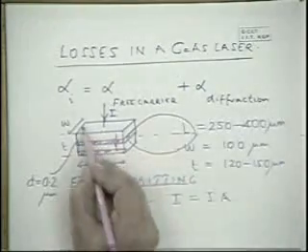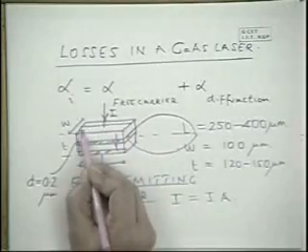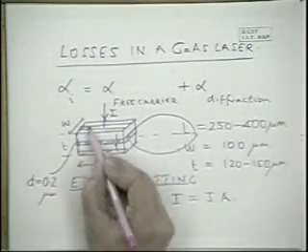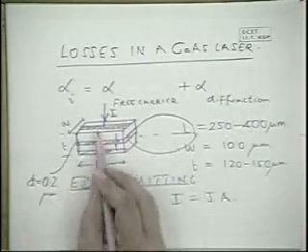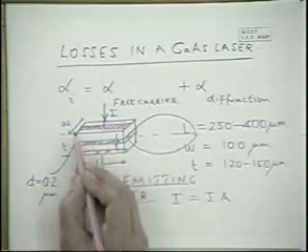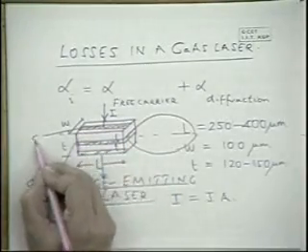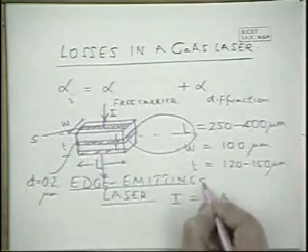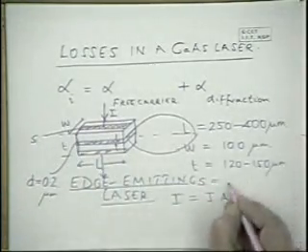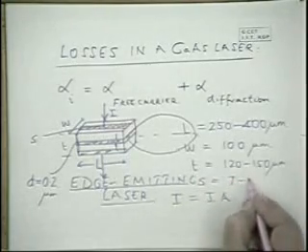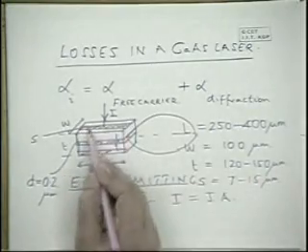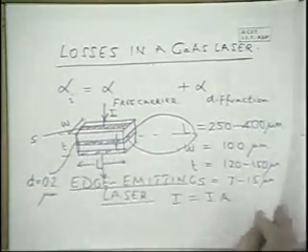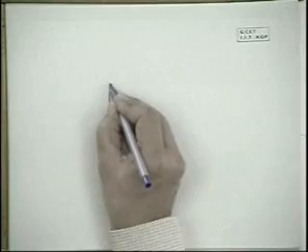So in order to reduce the actual current and increase the current density, what is normally done is you have what is known as a stripe geometry laser. The contact here is not the whole. Let's call the stripe width S. S is of the order of 7 to say 15 microns. This requires photolithography. The benefit is seen when you look at the laser front on.